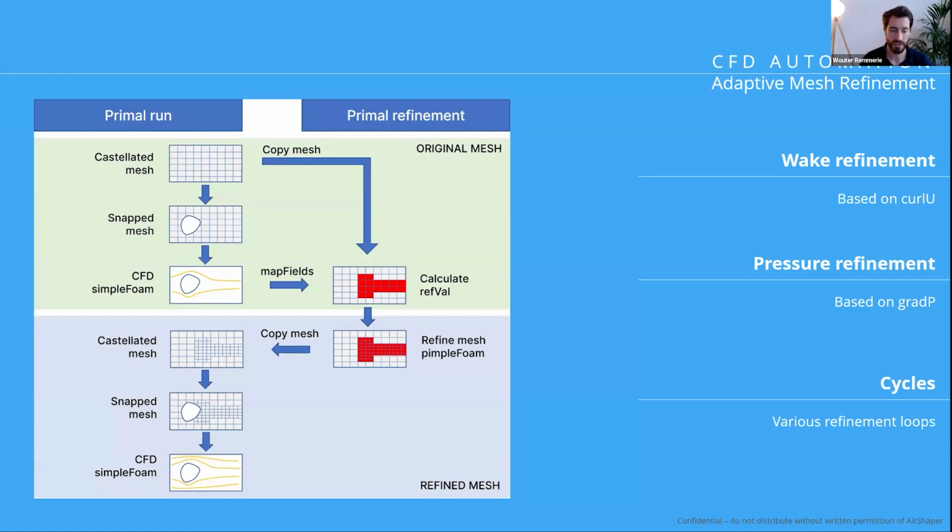We made an open source library to be implemented on OpenFOAM, where we refine both the volume mesh, which are the cells in space, let's say, and the surface mesh, which is the cells which are touching the surface. They actually create a surface mesh. Both of those are being refined in our system. And we have 2 types of refinement that we implement.